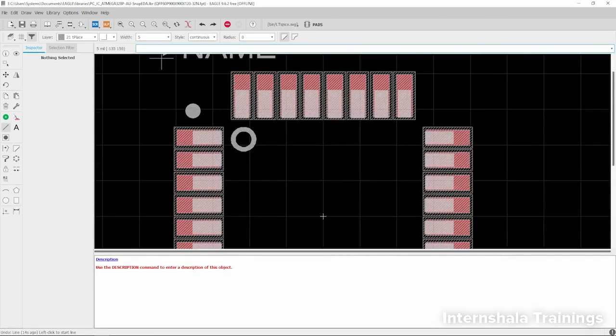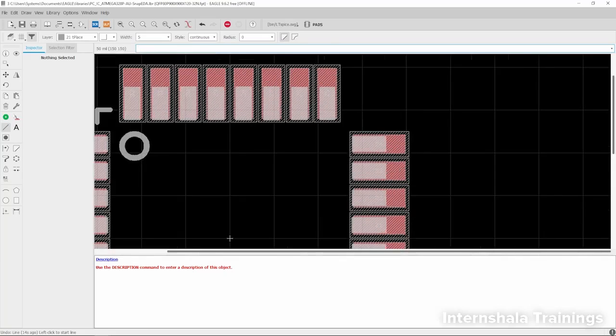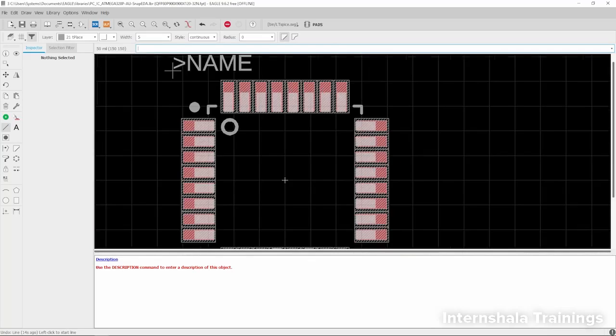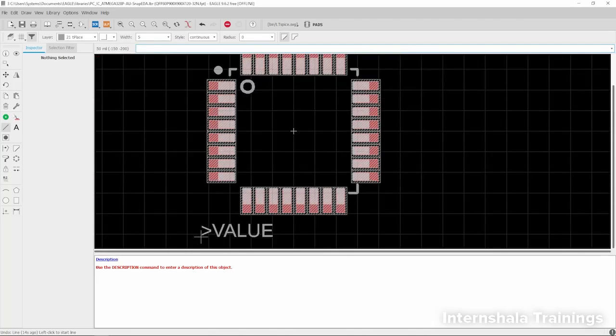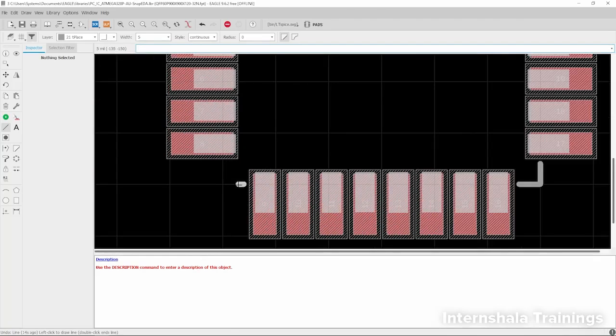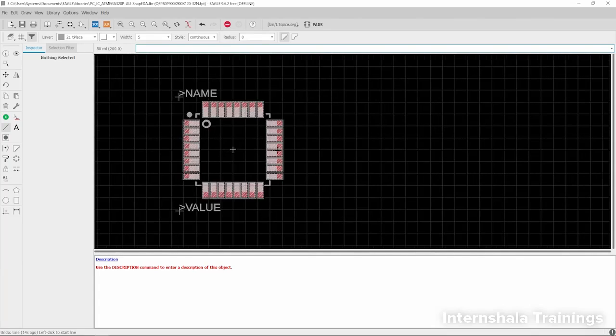Generally, whenever we create a footprint, there are some standards, and we need to follow those standards. It's not like you can create it in any manner. You need to follow the datasheet. In the datasheet of the IC, it will be given what the different specifications for the footprint are, like the size of the pad, the length of the pad, and the width of the pad. So considering all that information, you need to create the footprint. So that's basically how we do the changes in the footprint. Just to show you the process, I have done some changes in this footprint.